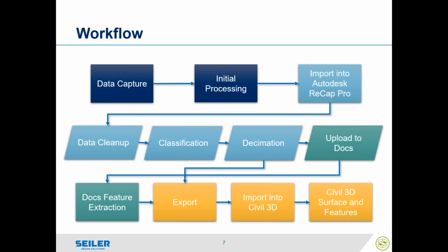So a typical workflow processing, either from TBC, Pix4D survey, or virtual survey, is to decimate that point cloud. Out of my 4 million points, I'm going to take an average of maybe 1,500 points or 4,000 points scattered throughout the site. Think of it, when you're out in the field surveying with a traditional rover or total station, you're not picking a point every 1 centimeter square. You're doing a 25 by 25 grid or a 10 by 10 grid, or you're running down line work every 10 to 25 feet. You're getting a representative sample of that.